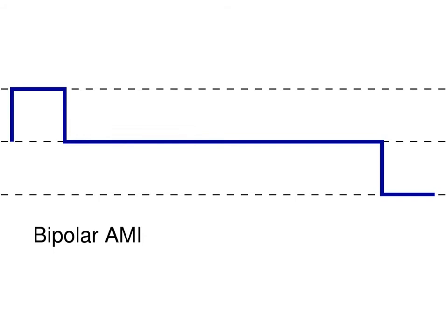This is what the receiver receives. So the receiver has a clock trying to determine every 2 milliseconds the next bit, but it may not be exactly synchronized with the clock of the transmitter. The clocks are not perfect. So especially over this duration, where is the next bit?